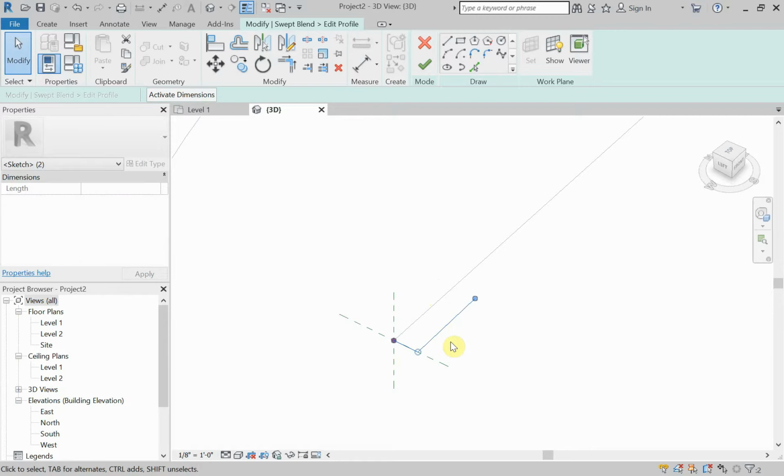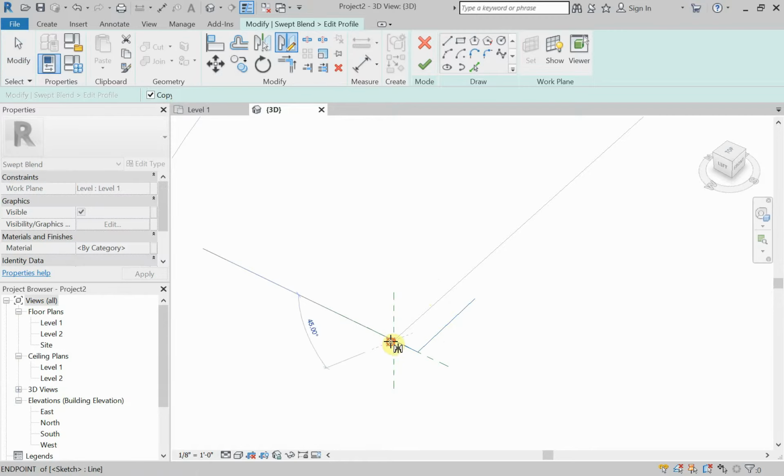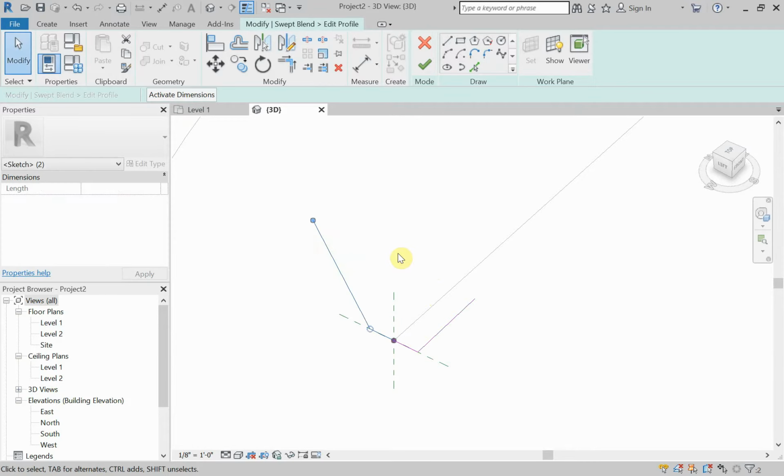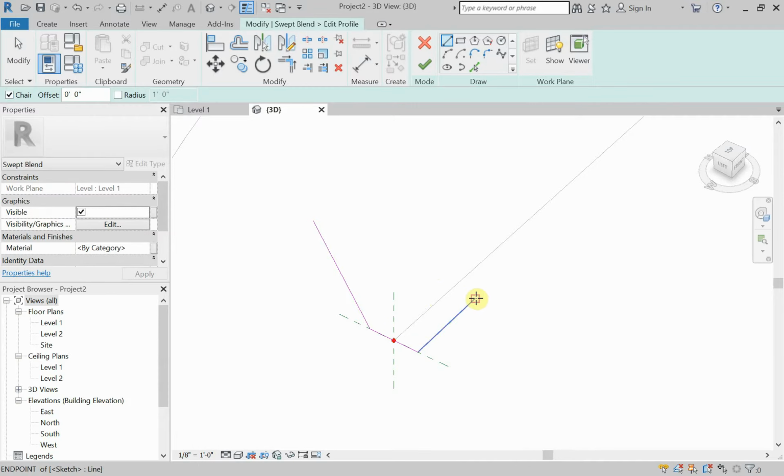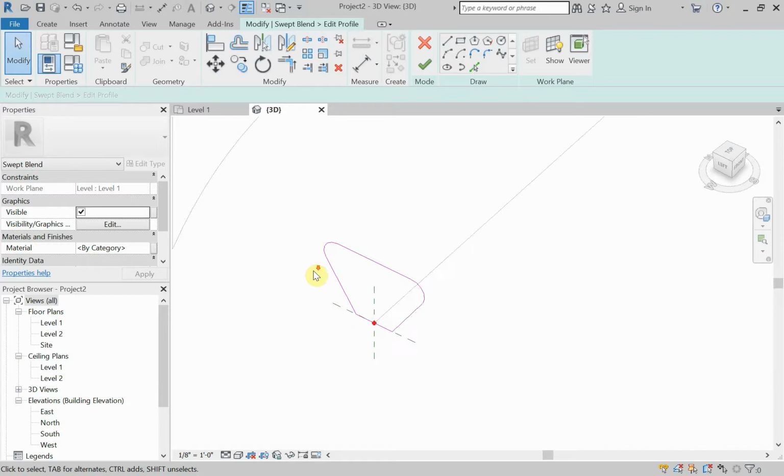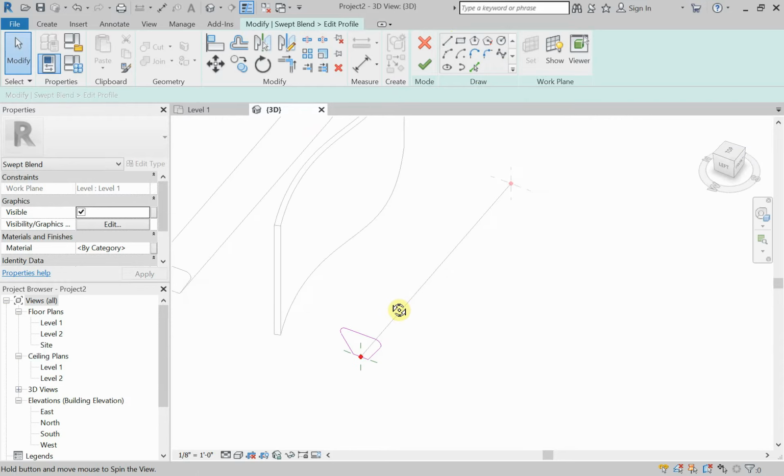And select both of those. DM for draw mirror axis. Go right down the middle there. Draw my line across the top. I used the shortcut LI for line that time. I didn't select it from up here. Alright, let's fillet those corners. Like how it rounds exactly to 3 inches. I do like that. So that would be part of my love relationship with Revit right there. I'll put that in the love category.